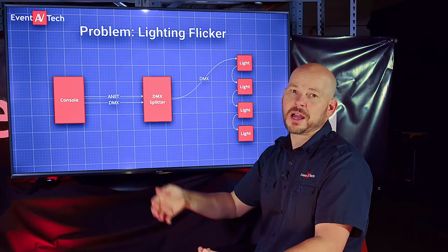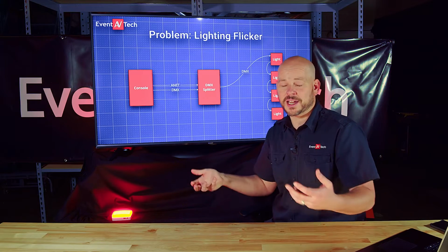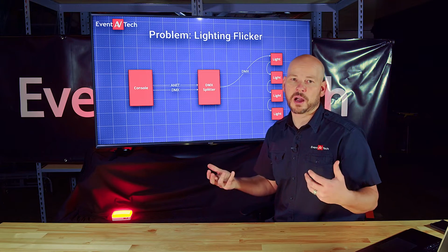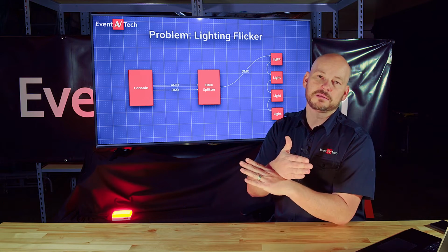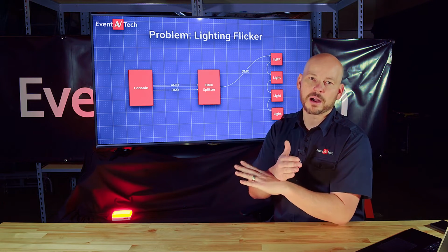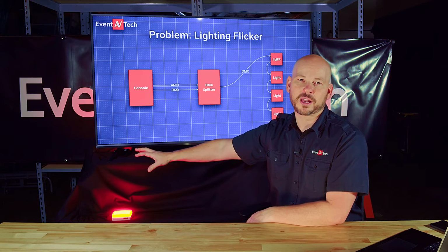And so the fixtures, by slowly taking one fixture out at a time, one element out at a time, I was able to discover when the problem stopped. Then when I discovered that the problem stopped, I knew, okay, from here on, I've got something. I actually had to start taking apart the set design and figuring out where the problems were. And I found out that eventually somebody had swapped the red and the black wire, and now they were doing the opposite things, and we just created problems all the way down the line.